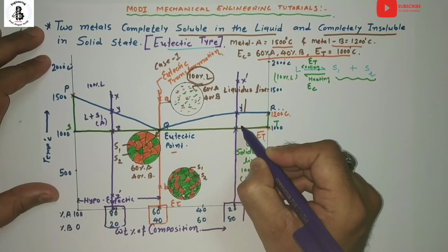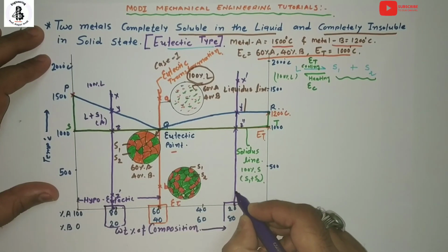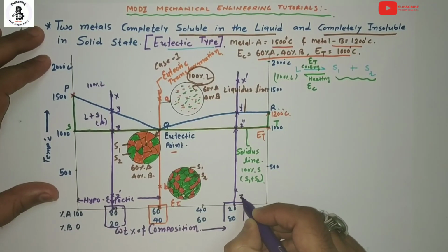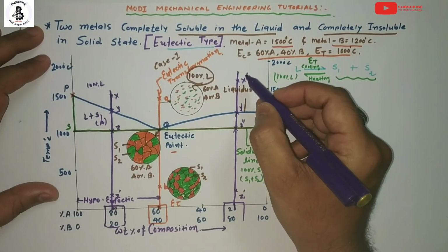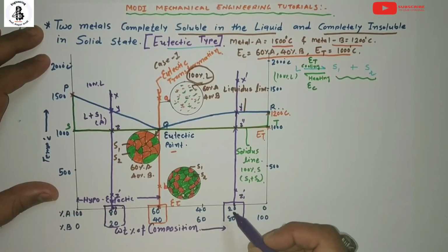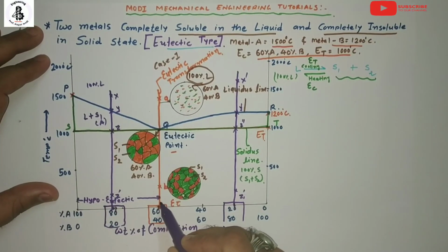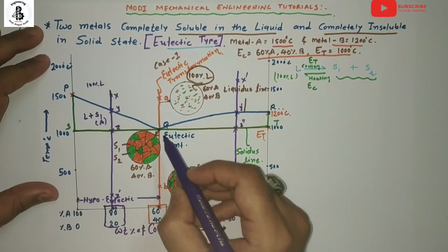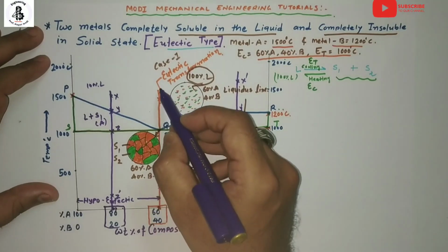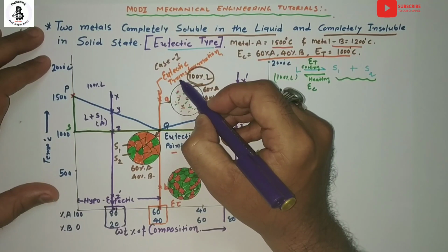Similarly onto the solidus line, Z double dash, because Z dash is already here, and at room temperature that will be Z1 dash. So this is our case number 3. So one line that is drawn before the eutectic transformation line will be known as a hypoeutectic transformation. The transformation line which passes through the eutectic point will be known as a eutectic transformation line.